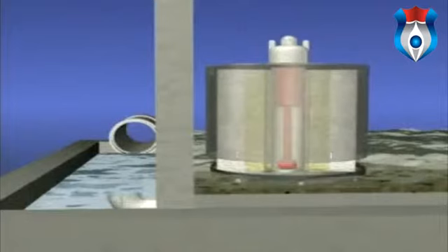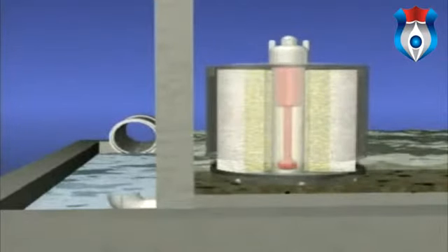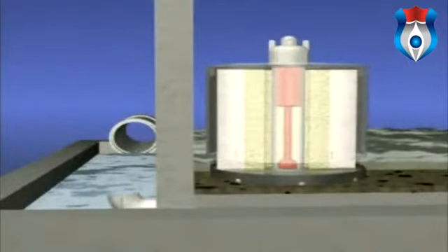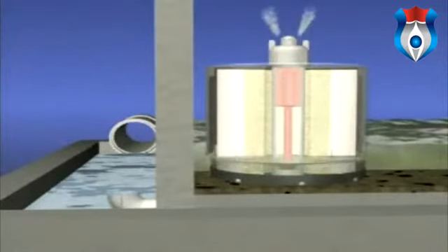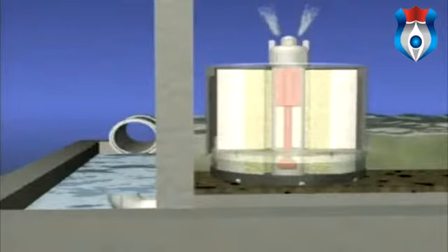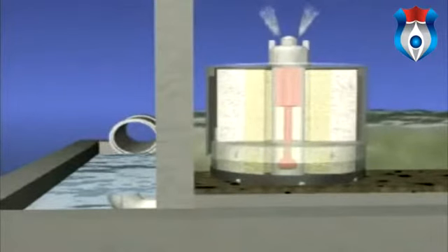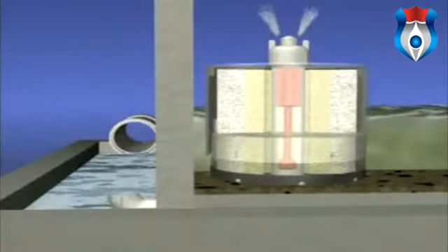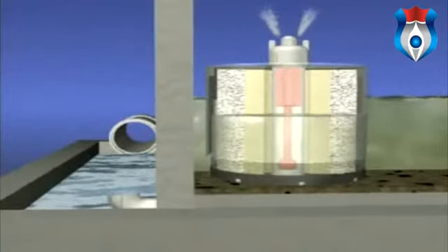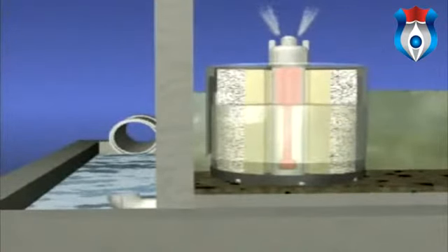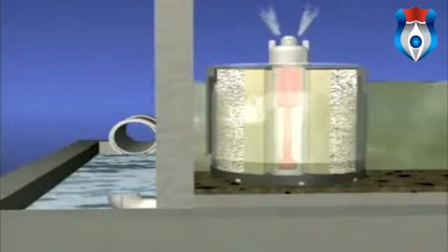During a storm, the float system in the center of the filter cartridge helps prime a siphon that draws the polluted stormwater through the filtration media and into a center drainage tube. The siphon mechanism is activated as the vault fills with water, and the trapped air is purged from under the filter cartridge hood through the air relief valve.